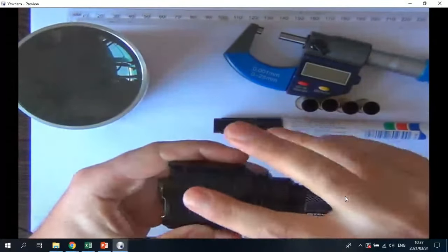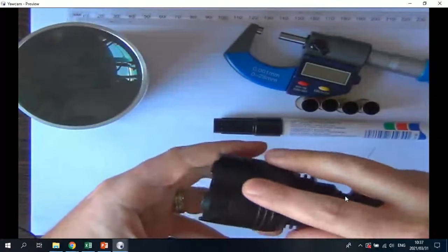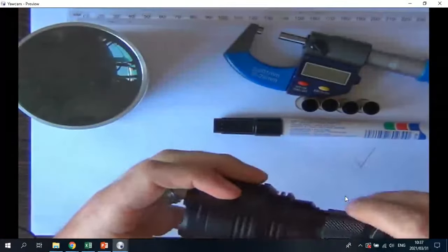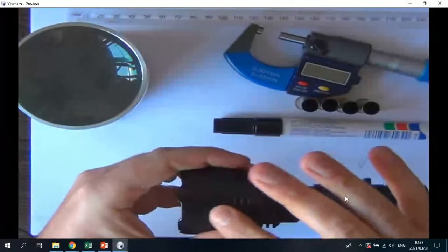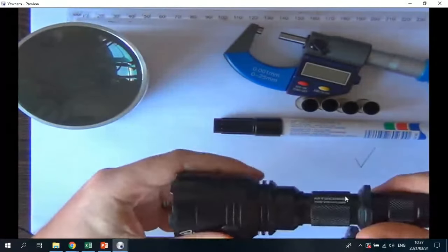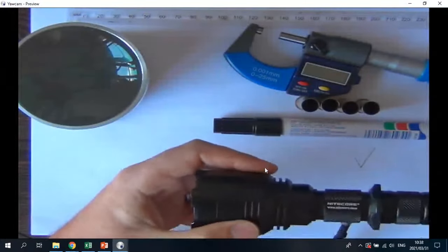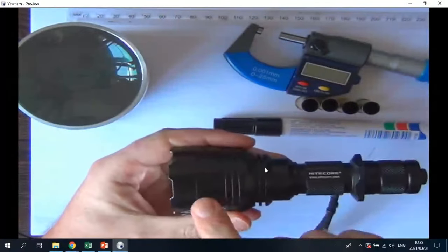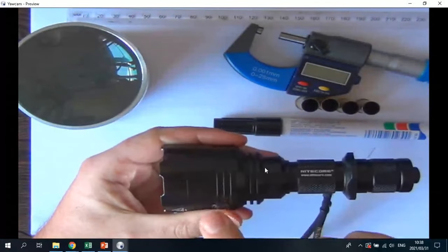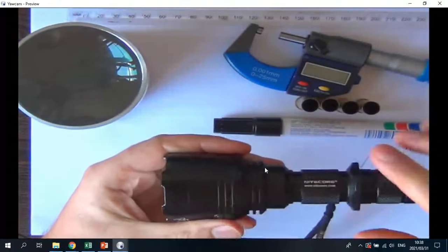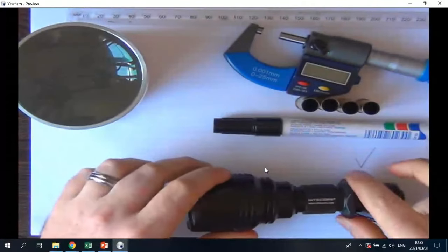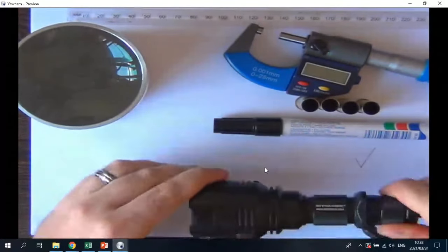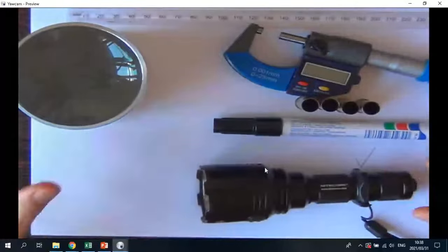So if it's too smooth, then it's going to start to slide out of your hands and not give the nice matte finish that it has over here. Okay, so this surface finish was obtained with an electroplating kind of process, although it's not specifically a plating process, it's an oxidization process.